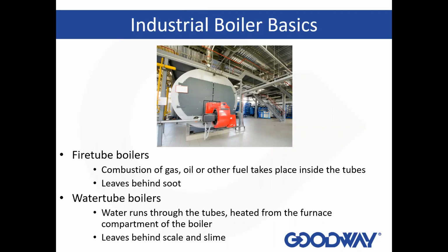On the other side, you've got water tube boilers, which run water through the tube and are heated from the outside. What can get inside those tubes are mineral deposits that build up over time. Again, what it ends up doing is insulating the tubes and hurting the efficiency of the entire system. So you've got two different types. One is what we would call a dry cleaning, which is a fire tube, where you're cleaning soot out of a tube. And one is more of what's considered a wet cleaning, where you're cleaning mineral deposits, slime, algae, mud, that sort of stuff out of the inside of a water tube boiler.